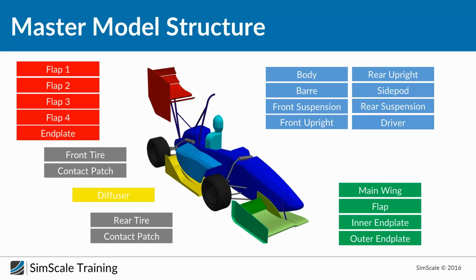You have to make sure that you take off all these things, because they will add more mesh to your geometry and bad cells to your mesh. So make sure that you take off all the logos and the written things on the tires or any other parts in your car.